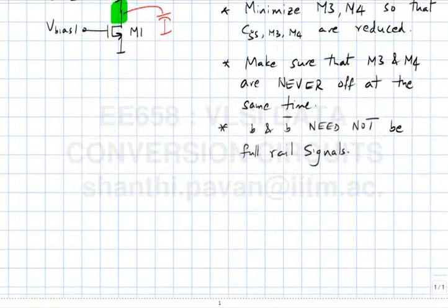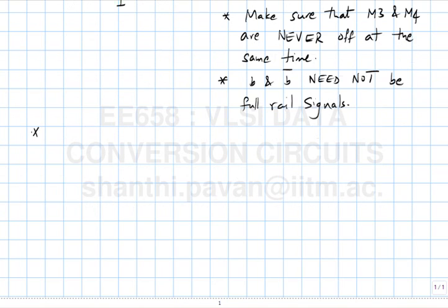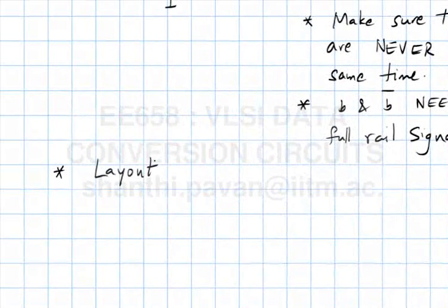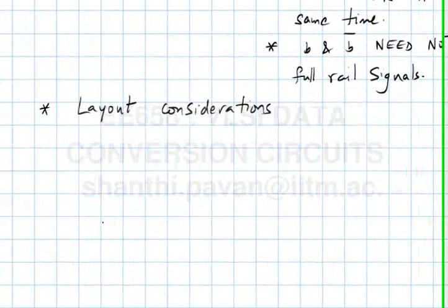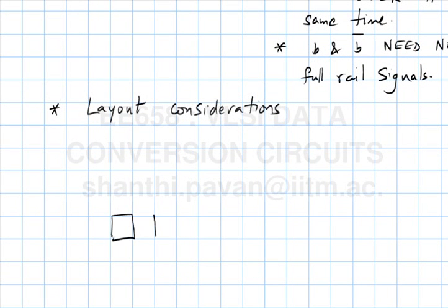So there are several ways in which you can arrange these transistor cells, these current cells. The ways in which you can arrange these cells motivate our next discussion. Let's see. So let's say you're trying to make a thermometer DAC, right? The simplest thing I can think of are simply current cell 1, current cell 2, current cell 3, current cell 4, and so on. Let me take the example of a 6-bit converter, so it's like 1 all the way to 63.